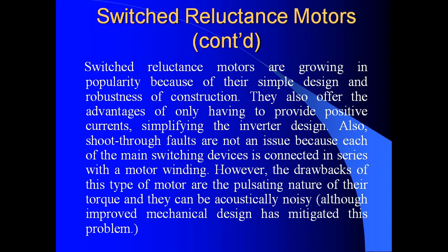Switched reluctance motors are growing in popularity because of their simple design and ruggedness of construction. They also offer the advantage of only having to provide positive current, simplifying the inverter design.